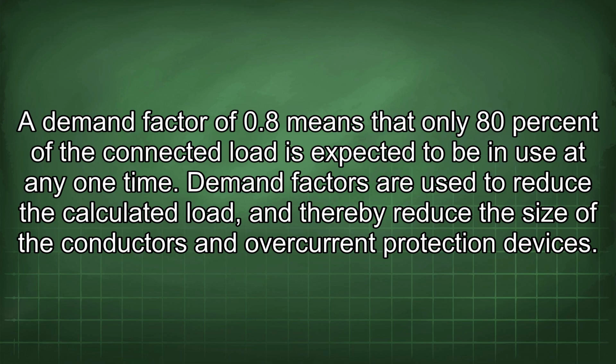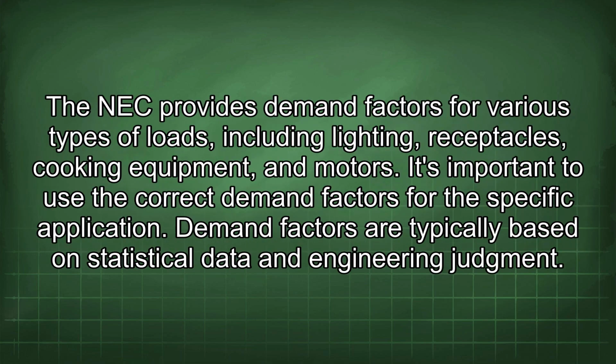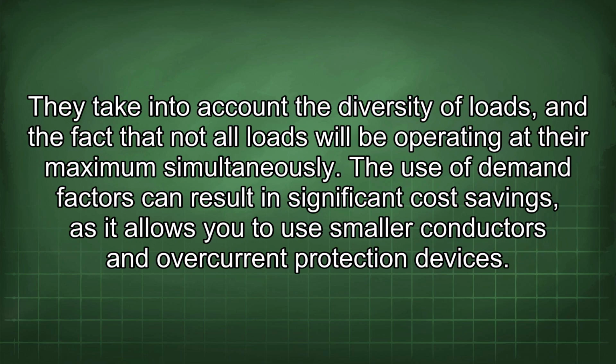Demand factors are used to reduce the calculated load and thereby reduce the size of the conductors and overcurrent protection devices. The NEC provides demand factors for various types of loads, including lighting, receptacles, cooking equipment, and motors. It's important to use the correct demand factors for the specific application. Demand factors are typically based on statistical data and engineering judgment.